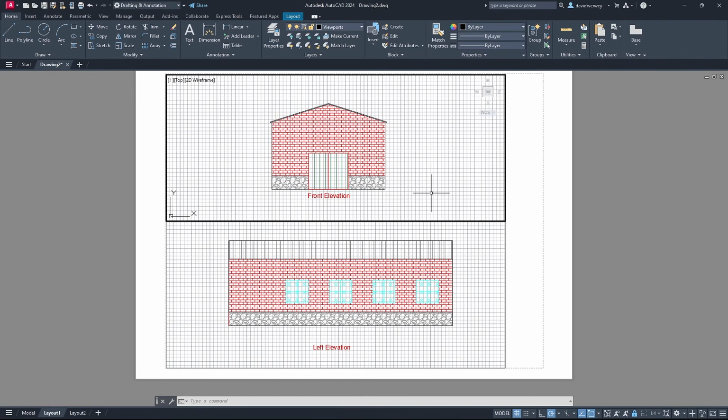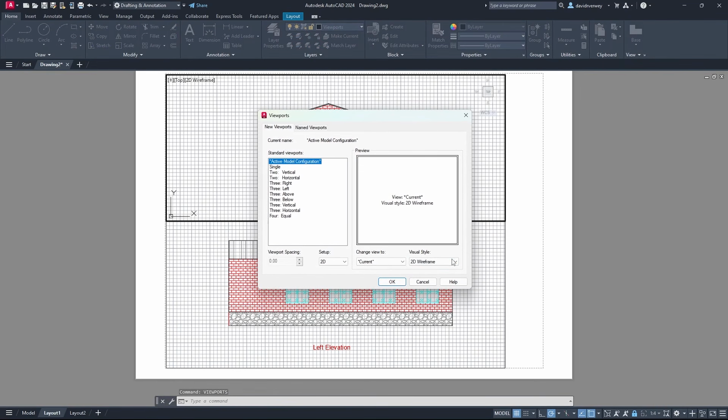When you're putting down viewports, just type in viewport in the command bar and create a new viewport, as I did there. So when I type in viewports, I can just click viewports, and then I create a new viewport. We're doing single, but you can also see that there's vertical, horizontal. I could have just made one of those. You can do 3, you can do 3 again, above, below, vertical, horizontal, anything else, whatever you need. But that's what we're doing.